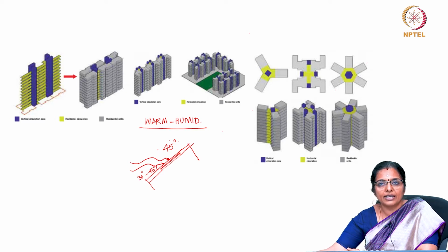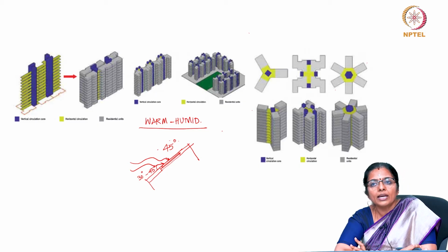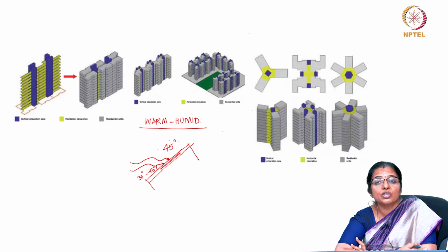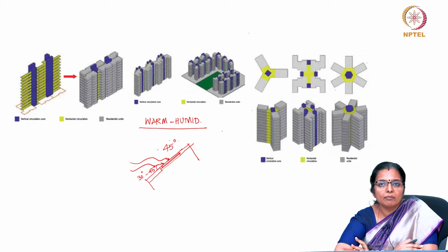Then the other criterion is that where a predominant wind direction can clearly be identified, the long side of the building should be arranged across that direction, because your main aim is to capture winds in a warm humid climate. In this case, a reasonable compromise should be made based on the detailed analysis of the specific situation.